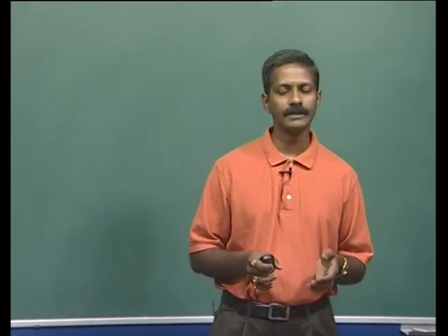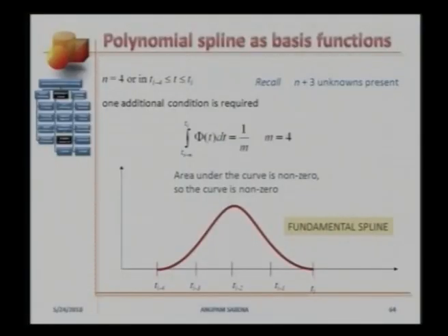If you look at this figure here, we introduced 3 conditions on the left and 3 conditions on the right. What were those 3 conditions? The position, the slope, and the curvature at the 2 ends of a B-spline basis function. In this case, this is an order 4 or degree 3 B-spline basis function.